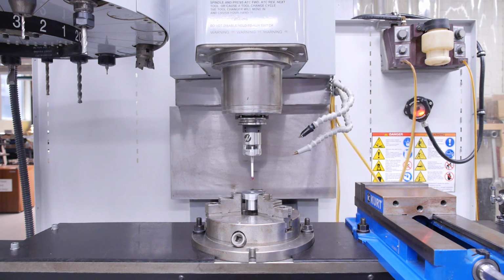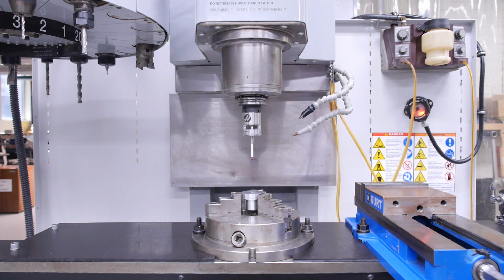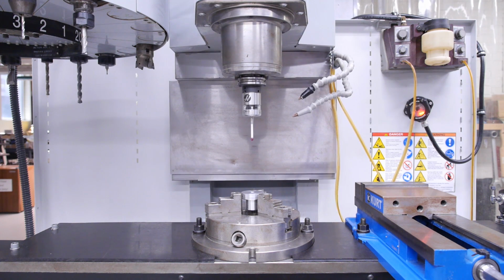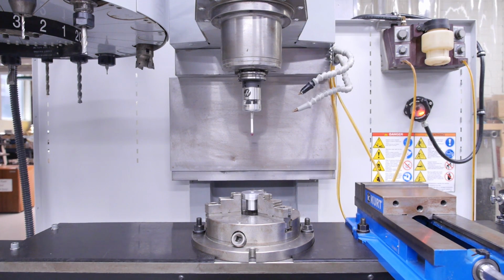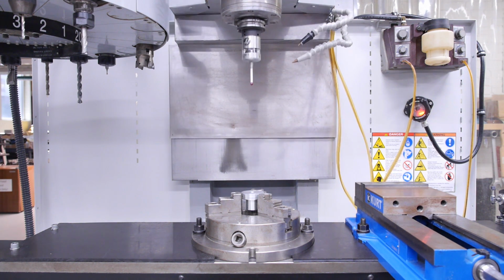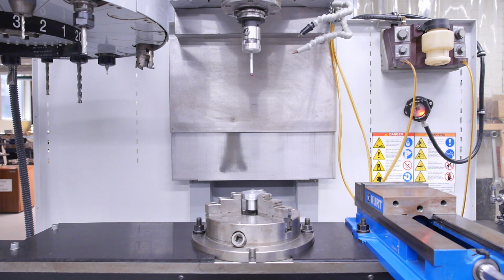Once the probe measures the top surface of the workpiece, it rapidly retracts and stops at a distance of 5 inches away from the part to allow you to answer any questions the students had about the probing cycle before pressing the cycle start button to continue with the tool change.